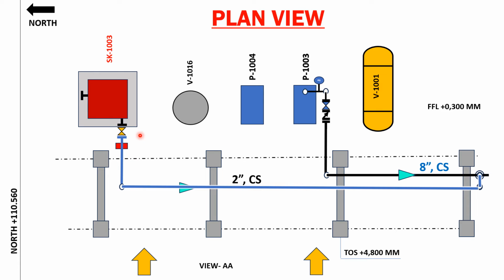Generally, lines with a temperature less than 100 degrees Celsius will not have such issues. You just have to provide a support as near as possible. But for lines which are above 100 degrees Celsius, you have to take this action very cautiously. So logically, what you have to do is provide a support which is as near as possible. Understand? Now let's go to the next one.